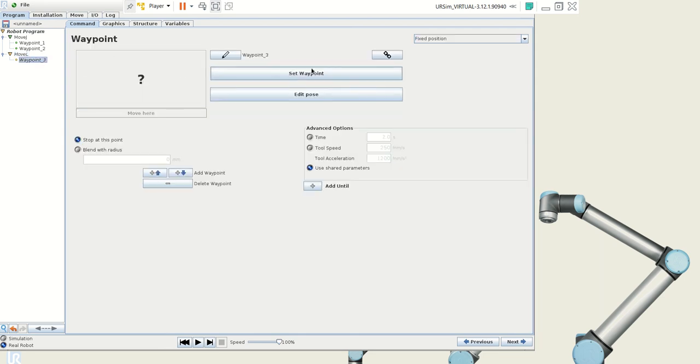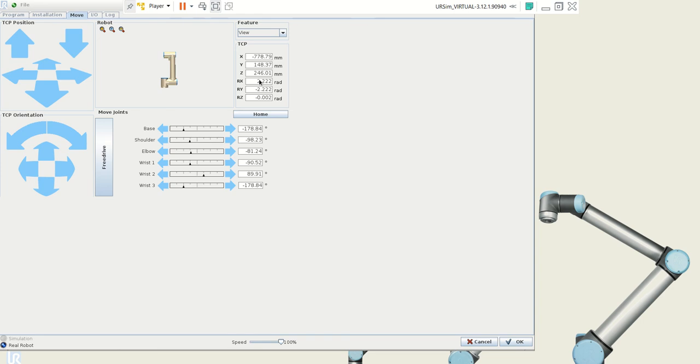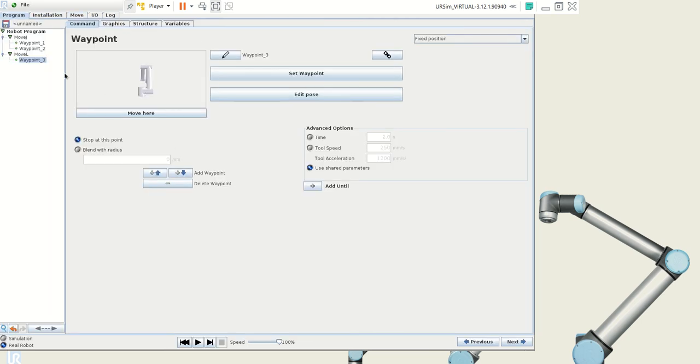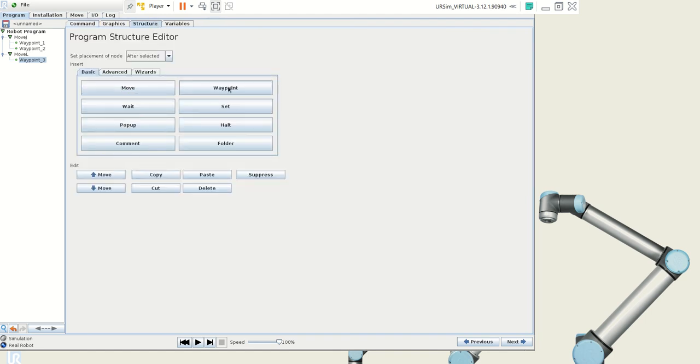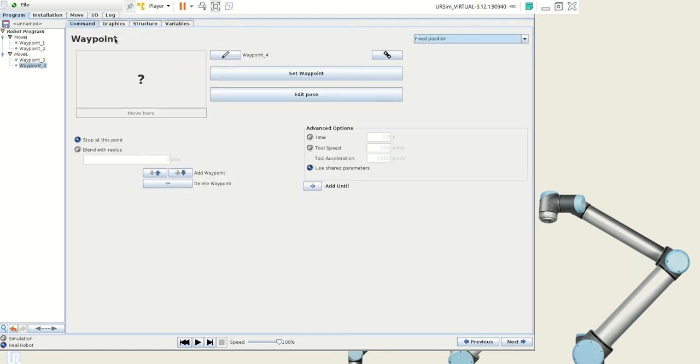Click on the waypoint, edit the waypoints, and then basically you're just going to come down a good bit. Again, you could make this an exact science if you wanted to, moving your Z coordinate as far down as you want to go. I'll say roughly minus 100. Click OK. Again, we'd imagine that would be picking up the part, and then it has to come back up.